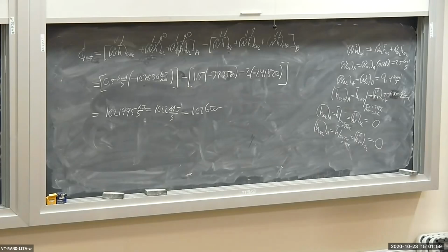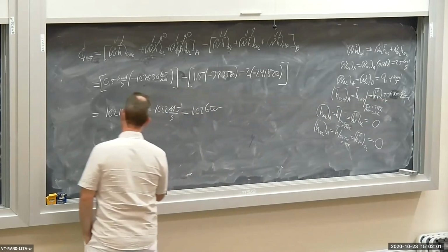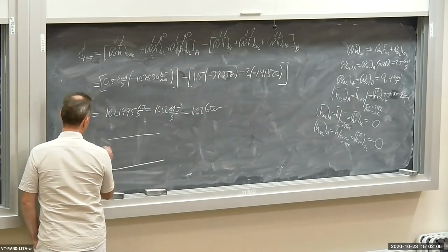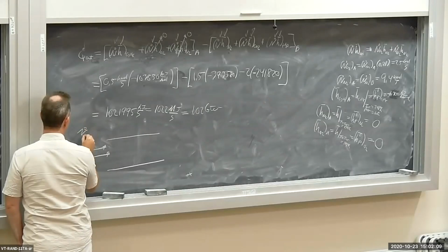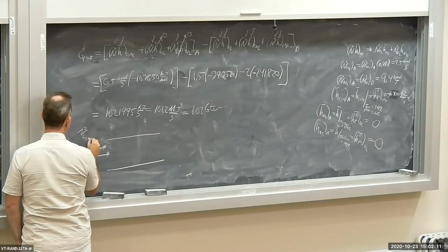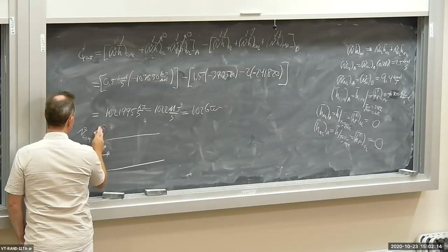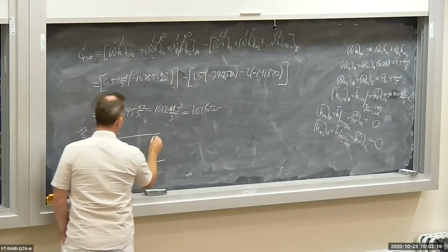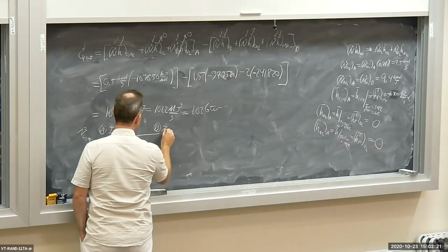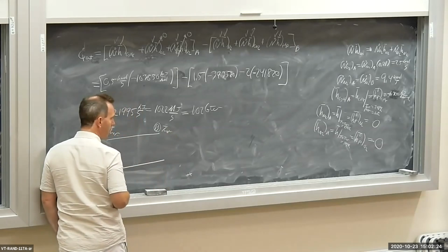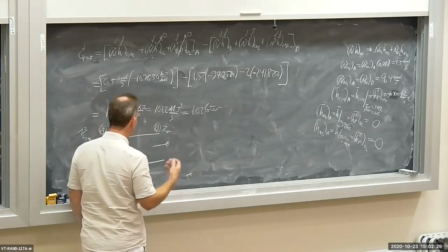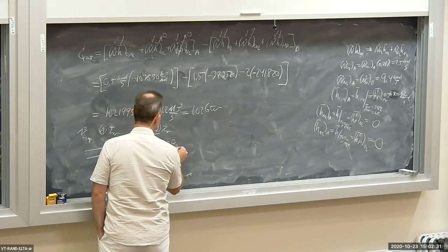So what's the situation here? We have a combustor. I have an N dot for my propane, C3H8. The inlet state is at Tref. The outlet state is at Tref. I have various products of combustion, CO2 and H2O. Remember, the H2O is a vapor.